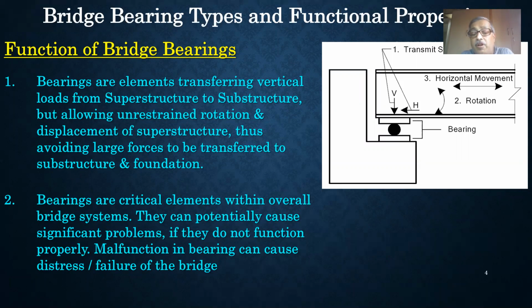Vertical load will get transferred whether you have bearings or not. As an example, in buildings, we do not provide bearings in the majority of cases because the spans are of the order where the rotations and the lateral loads caused by the deformation are not so significant. But in bridges, where the spans are long, the rotations and the translations are going to have significant effect on the substructure and foundation in case you do not release those deformations. And that is why the need for bearings.